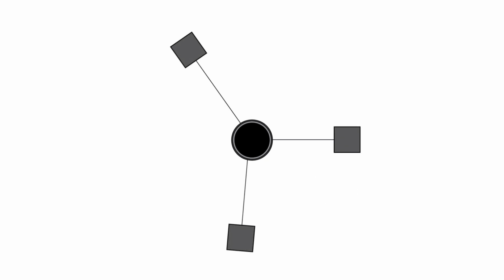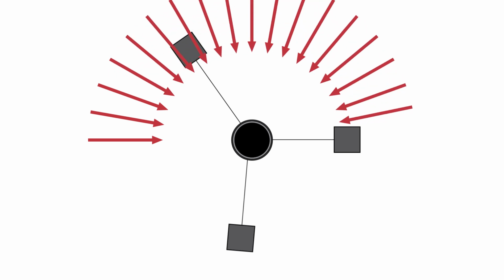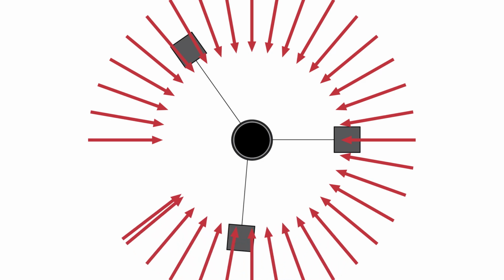If the deadmen are not symmetrical, then things become more complex. When they are not symmetrical, we need to look at all of the load direction angles to ensure we capture the worst case. We select the angle increment that needs to be considered in the analysis settings screen when we perform the analysis. If we select 10-degree increments, since there are 360 degrees around the stack, we have to consider 36 different load directions for every load case.